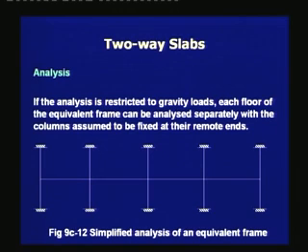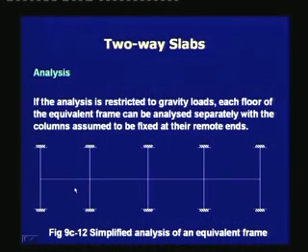That means for a particular floor level, we can analyze that by itself, and what we assume is that the columns at the far ends from that floor are fixed. That means we are not considering any influence from the loads of other floors on the moments of this floor. And once we analyze a typical floor like this, it gives the results for most of our floors, because usually the loading is similar for many floors, and hence our calculation gets much simpler as compared to analyzing the complete frame.